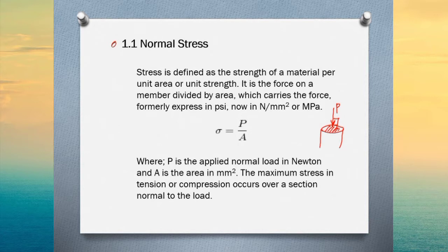So the force, which is usually applied in Newton, in this area, which is normally expressed in mm square. So we have here the force in Newton and area in mm square. That's why this normal stress is in megapascal.